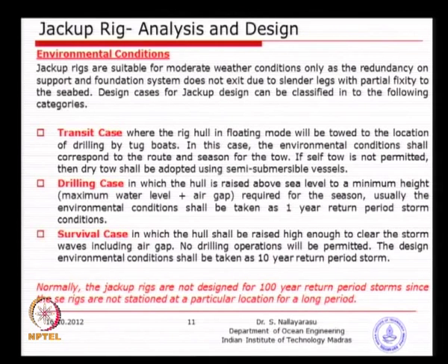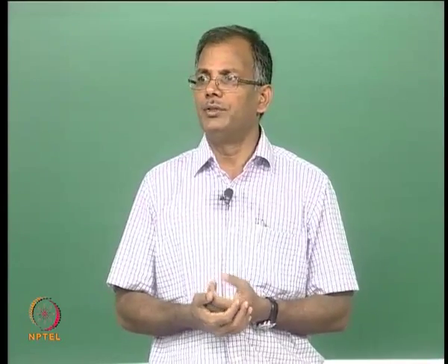That means you will design the jackup rig with complete drilling loads plus your 1 year return period storm conditions, wind, wave and current, or you will design for 10-year return period environmental conditions, but no drilling operations. What exactly is the difference? Drilling operations not taking place means there will not be any fluid in the circulation system.